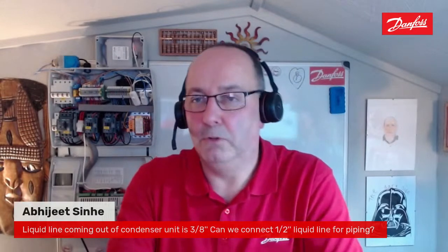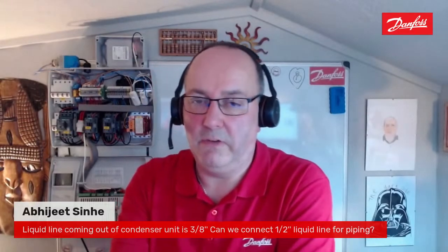We are talking refrigeration, we're not talking AC. AC is a totally different set of rules, if you like. AC units are generally expanded at the condensing unit. In refrigeration, we expand at the evaporator.